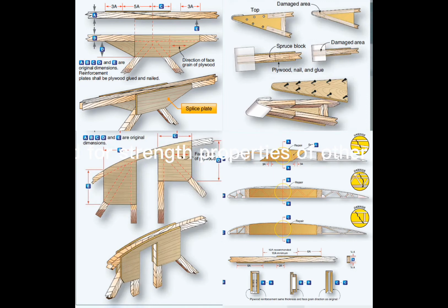What species of wood is used as a standard for strength properties of other species of wood used in aircraft structures? Spruce is the standard of all wood. Is northern white pine an acceptable substitute for spruce? Yes, only if the pine is a larger size.